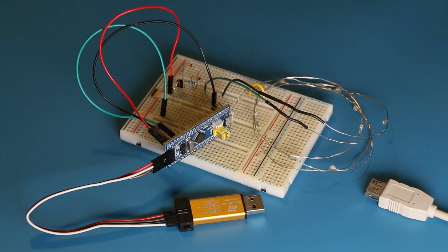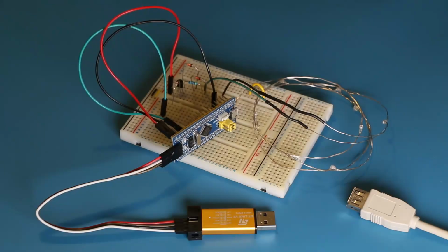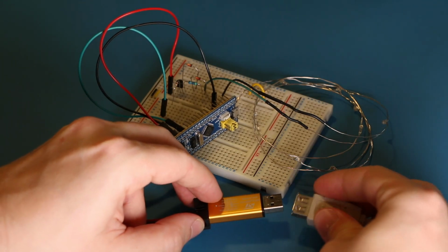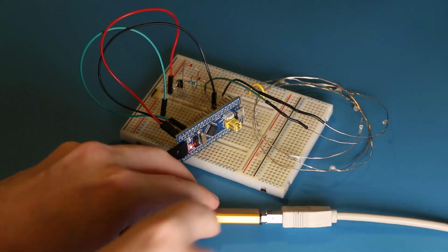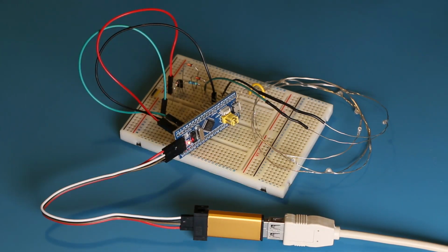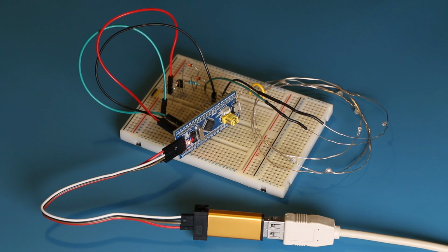In this video I'd like to start with building a very simple bit banging application which will hopefully be able to control these LEDs. In the previous video we never powered the LED chain, so I'd like to do that now quickly just to see what happens. I'm going to use this ST-Link to provide the power, and you can see that the LED has come on the STM32. Nothing in the chain is happening though, which indicates that either they require controls and they start or they power up in the default off state, or perhaps that clock that we were looking at earlier on the scope is missing.